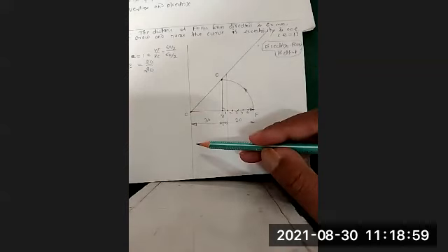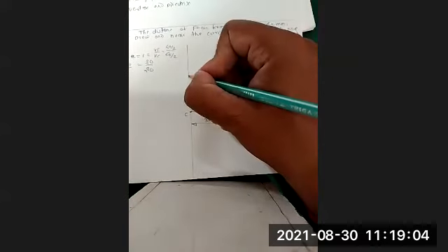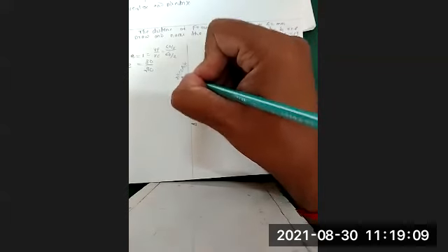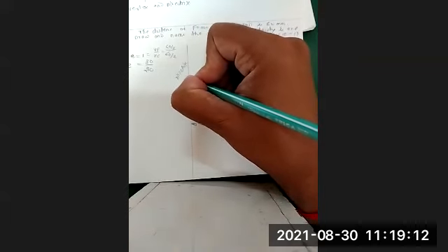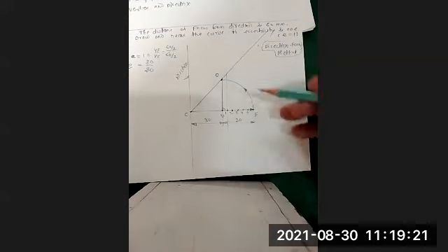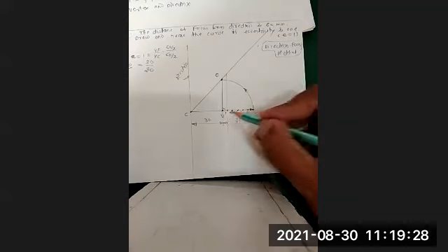And we have moved further by drawing this line first. Draw this line. This line indicates your directrix. This is nothing but the directrix, and the point on this directrix is selected here, point C. Then we have taken the distance C to F of 60 millimeter, and as the eccentricity is 1, we have taken this 30-30, right?